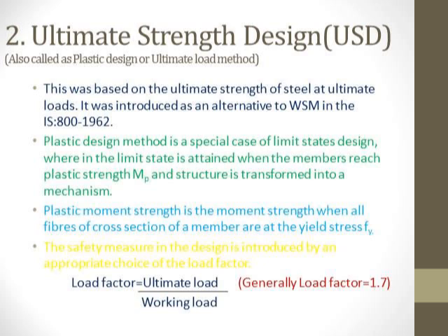It also depends upon the working load. If dead load plus imposed load and the seismic load is used, then the load factor is 1.3. It is the minimum load factor which can be used, and if it is dead load plus imposed load, then 1.7 can be used.